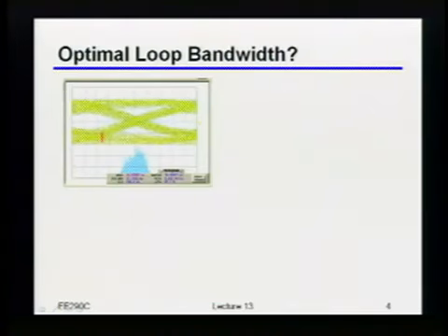In other words, I could still have a lot of residual ISI. Because of that, if you looked at the histogram of the time crossings, in other words, the jitter at that edge position, you see it's actually really ugly, right? There's all kinds of junk happening over there, okay?